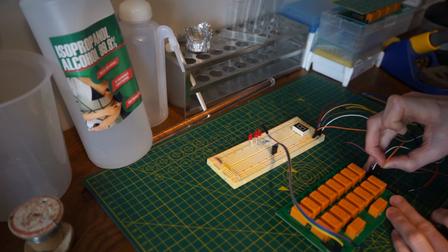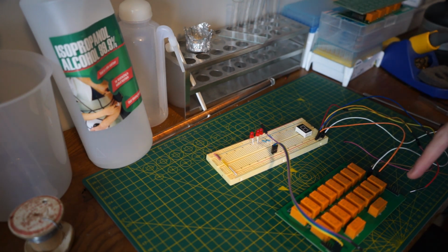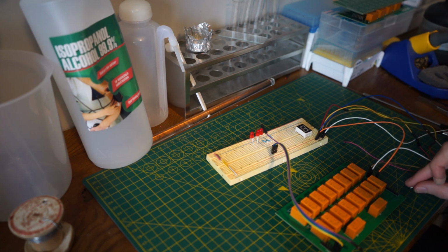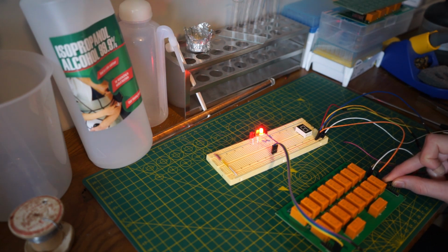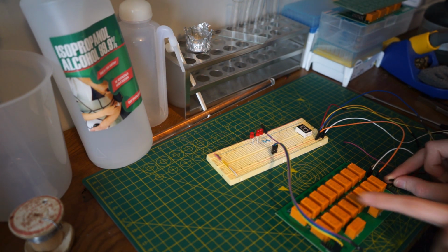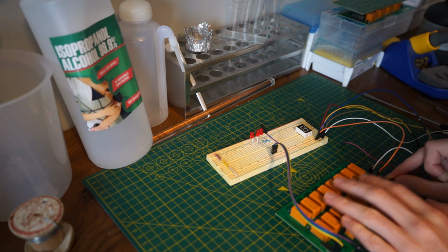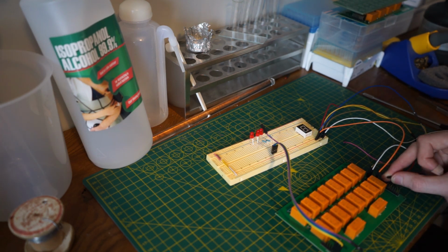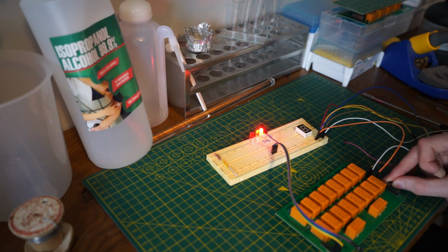I don't think it'll be a problem though, because the inputs are put into this board well before we need the outputs out. And when we first do an OR, all the lights seem to turn on for a split second, which I found the problem. We need diodes to prevent backfeeding in one part of the circuit, which I will do for the next version, but for now I think this will be fine.